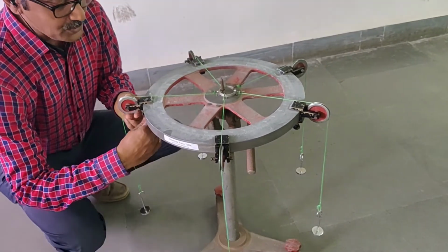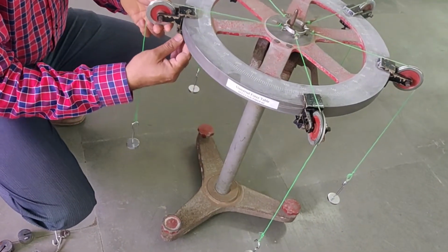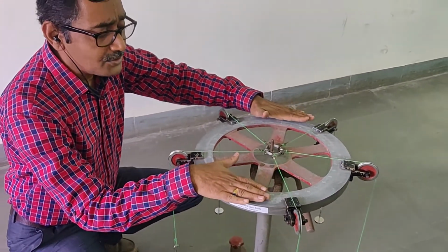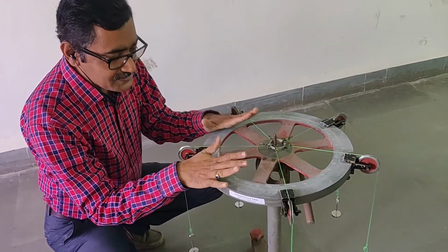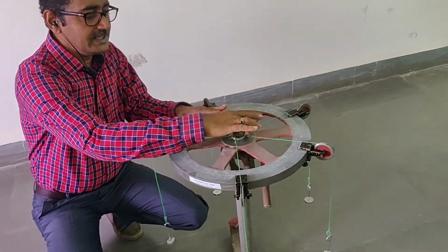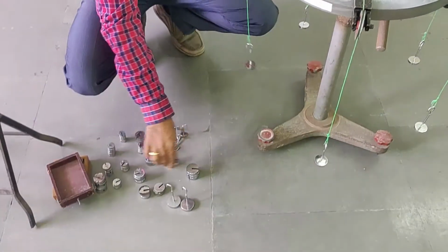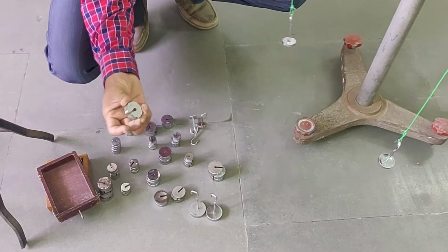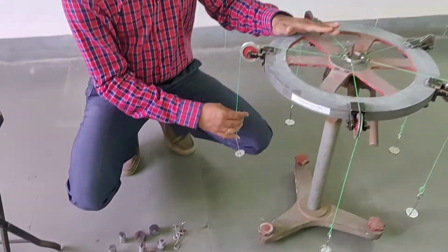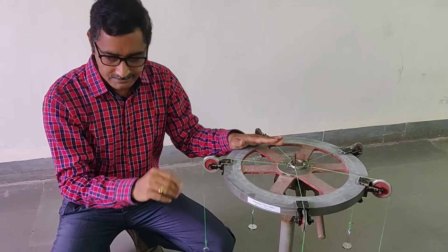Now the position of this pulley, we can loosen this screw and change the position, meaning the angle of this force, and we can tighten it at a particular position. So this is the universal force table. Other apparatus which we require are the pulleys, weights, thread and this ring which we have to settle at the center. The different weights which we are going to use here are 100 gram, 50 gram, 25 gram and 10 grams. All these weights are in grams, and while doing the calculations, you have to convert grams into Newtons.